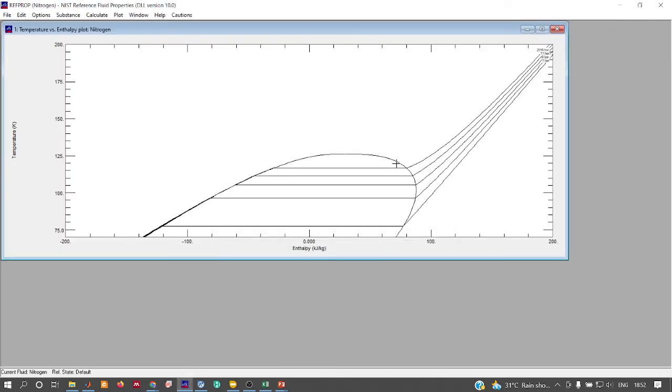Okay, see, in one case we are cooling it down. You are able to follow the pressures, right? So this is 6 bar, however I'm assuming it to be similar to 5 bar. So in one case we are cooling it down to 100 Kelvin and then expanding it. When you expand from 5 bar to 1 bar, you can see that you have some fraction of liquid. However, with just an increase of 1 Kelvin from here till here, you are completely into the saturated vapor region.